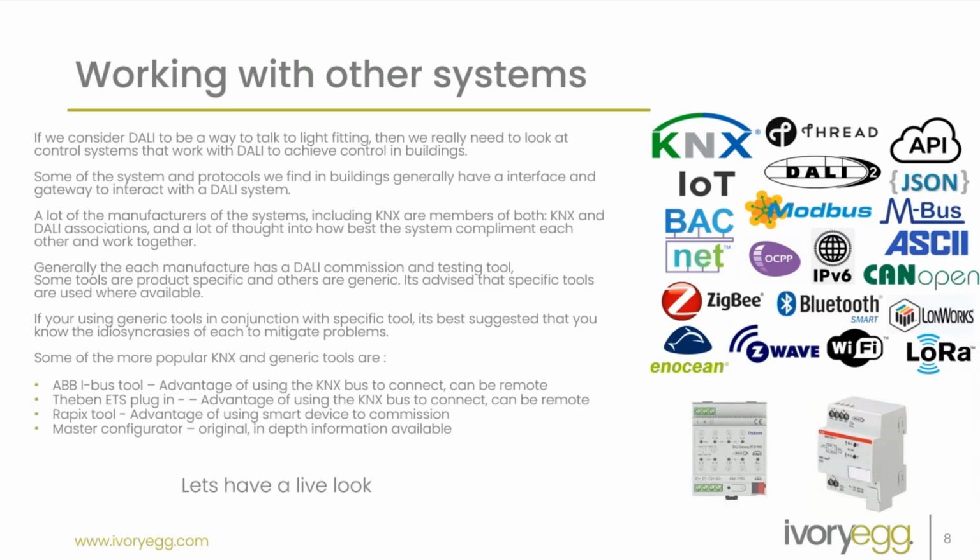Generally, each manufacturer has its own DALI commissioning and testing tool. However, we can do some short addressing and some things with others, but I would suggest that you use the DALI commissioning tool that comes with the device. Some tools are product specific, others are generic. It's advised that the specific tools are used where available.